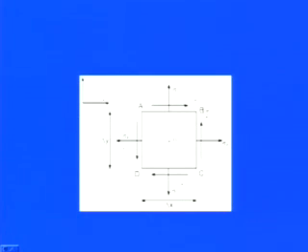So these 2 shear stress components are there. If we are discussing a simple plane problem where xy is there, how many stress components are there? In total we have 2 normal stress components and 2 shear stress components. So only 4 stress components are needed; no need to go for all 9 components. The 2 normal stresses sigma x and sigma y, and the 2 shear stresses tau xy and tau yx, are sufficient to describe the stress state if we have unit width for sigma x and sigma y in the corresponding x and y directions.